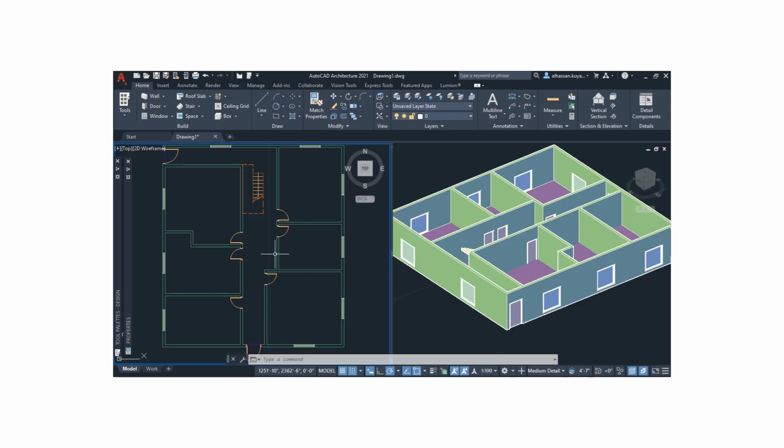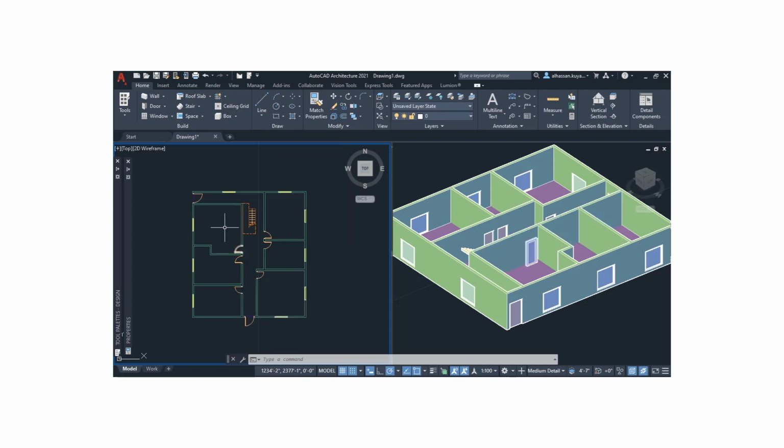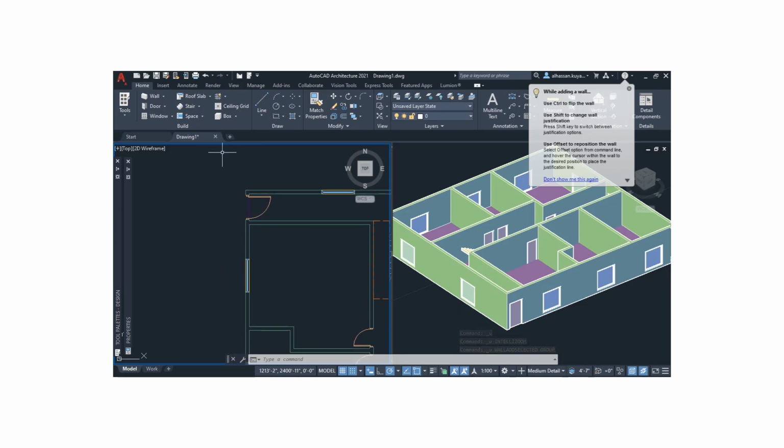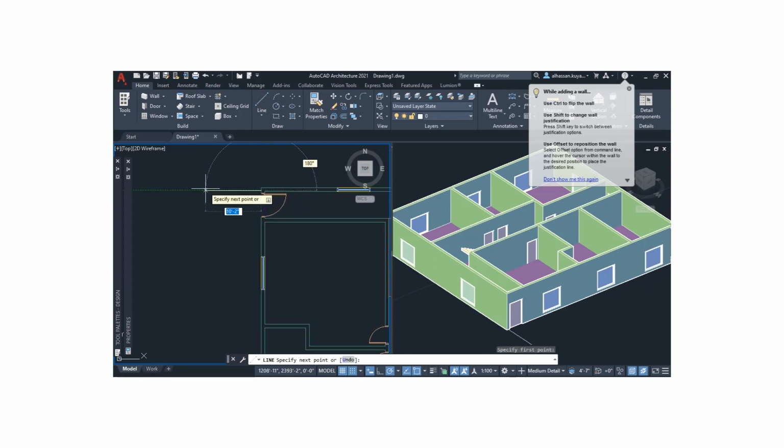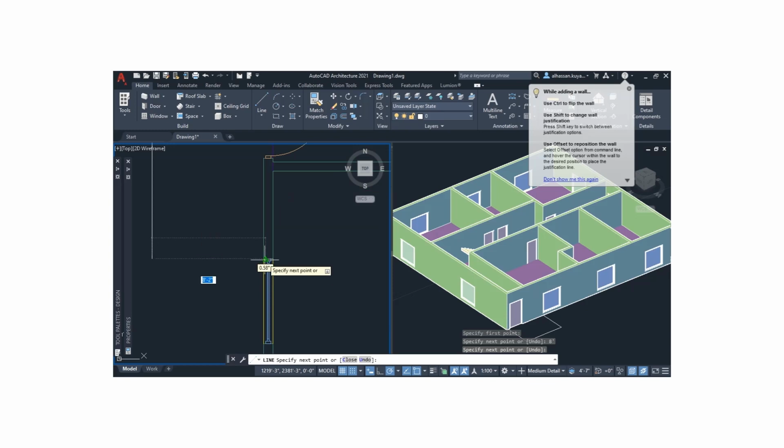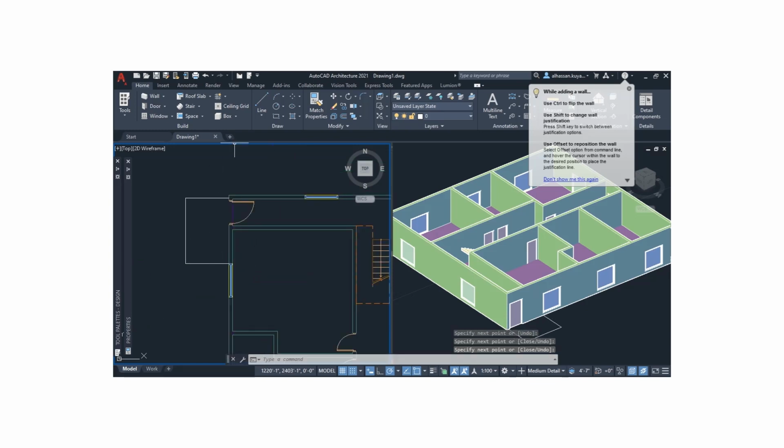We want to give a veranda. To specify a veranda, we create a railing. So to specify our veranda, we take line and trace where we want to position the veranda. So we go with 8 feet this way and come down, snap through here where we want it to stop, and here. So we take railing on the stair.